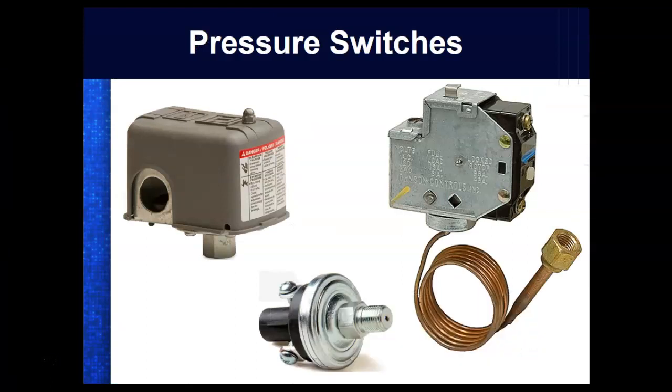So basically this deals with nothing but digital type sensors, like the pressure sensor that I gave, which actually came off of a compressor. You look at it, it's got low, it's got off and on. It turns off at 100 psi and turns on at 70. If you probably notice, all the hand tools you buy for your compressor are supposed to operate at 60 psi.